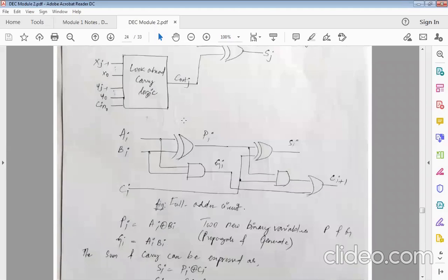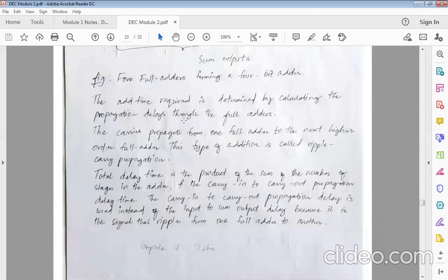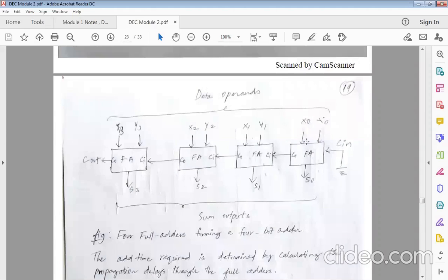So what is going to happen here? Let's come back to the diagram. Even this stage is dependent on only the first carry. This stage is also dependent on this carry, and this stage too. So once the Cout gets generated, I can get S1, S2, S3 executed in parallel. Anyway, S0 will come along with C0. As soon as this value comes and sits here, all these three stages will automatically get generated. Now, students, are you getting it? Is it clear?